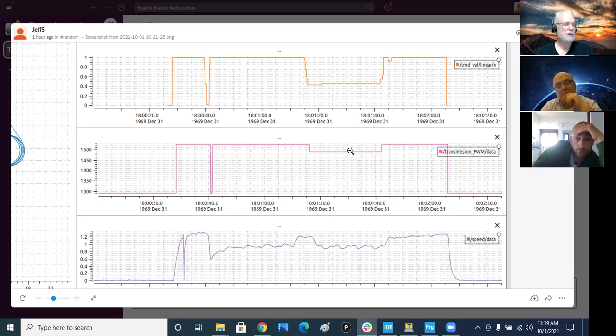So you come down to a certain point, and then it will start slowing down. But I'm guessing even this value that got scaled from 50% or 0.5 meters per second got scaled to this. I'm guessing that's at least 100% on the servo, and then this top one is beyond 100%. And that would explain why you're getting the same velocity of 1 meter per second here and 1 meter per second here, even though the joystick said to run it half a meter per second. So go back and remeasure your transmission to see where you keep increasing the number, where does it stop increasing? I think you've just gone beyond the limit of what the transmission will run. That's what this graph is showing me here.